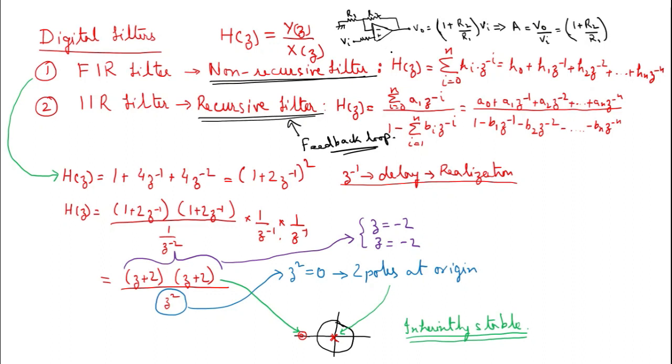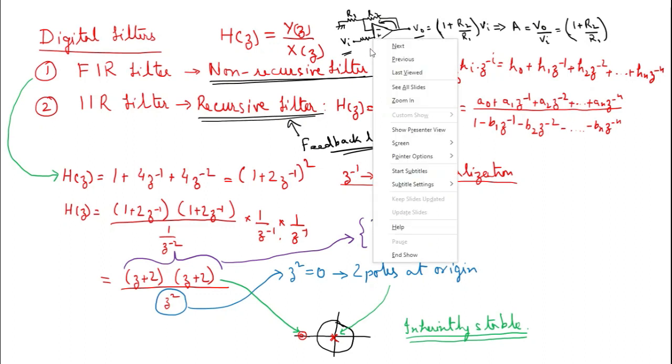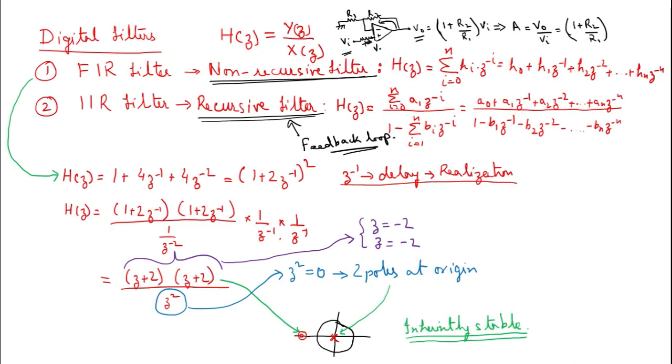Let us take the example of this non-inverting amplifier. If you see over here, the output of the system is taken to calculate the next output. We have Vi over here, and no current flows into the op amp. So at this position we have Vi, and correspondingly at the inverting terminal also we have Vi. Considering Vi is positive, in which direction will the current flow? The current will flow from Vi to ground. That means at the inverting terminal, no current flows either into or out of the system. So from where is the current being supplied? The current is being supplied from the output region. So the current flows from V0 to ground.